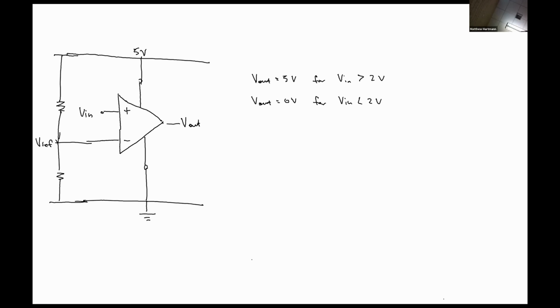Yes. Okay, so do you guys remember how voltage divider circuits work from Circuits 1? Or even Engineering 120. So we have something like this. We have 5 volts, a resistor, 2 volts here, another resistor, and then here's our ground, right? This is how all of your sensor outputs worked in Circuits 1.